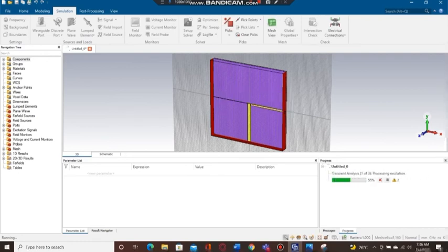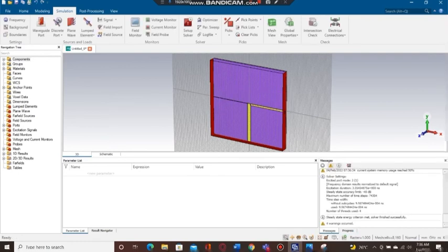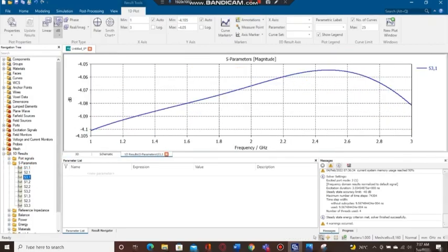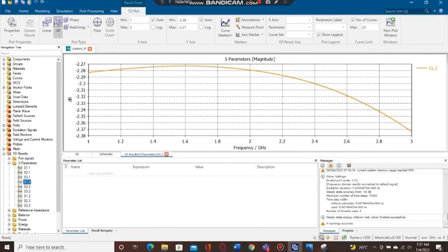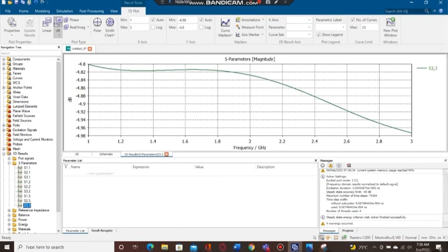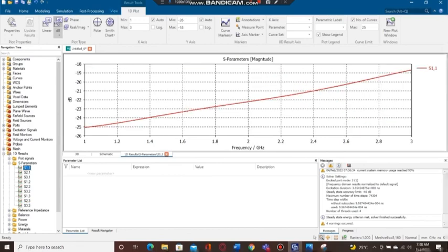The setup solver takes some time in order to simulate the microstrip line that we designed. Therefore, we obtain our S parameter graph based on the calculation that we did earlier for S11 up to S33 based on the matrix for scattering parameter T-junction power divider.